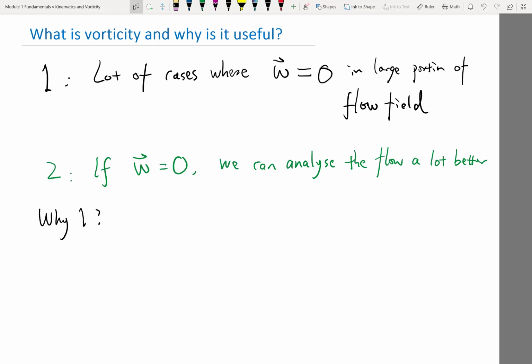And if you take the frame of reference of the free stream, then velocity is equal to 0 everywhere, and the vorticity therefore is equal to 0 everywhere. Okay, so if you have no vorticity to start with, and the viscous force is very small, then there is no vorticity that you end up with. That's what we are trying to derive, that the rate of change in vorticity in a flow field when there is no vorticity is exactly equal to 0.